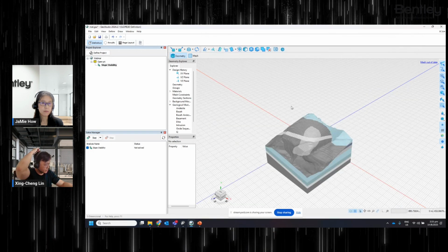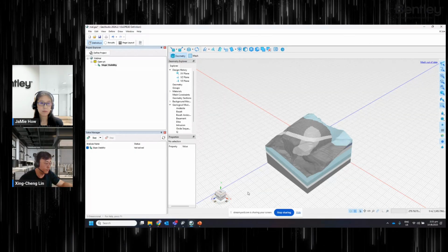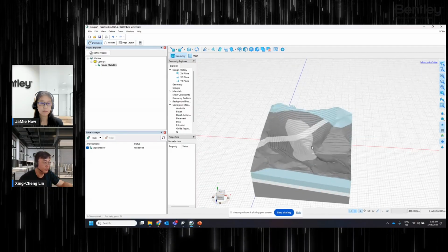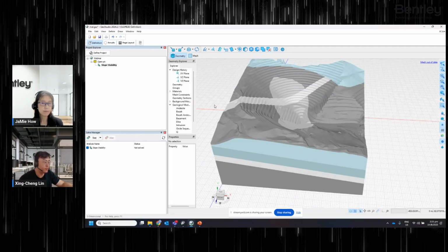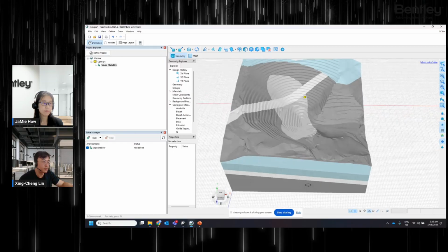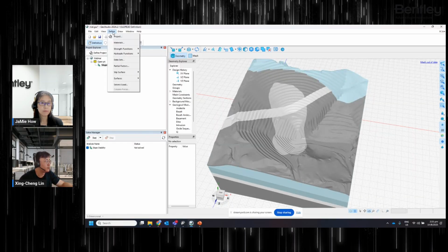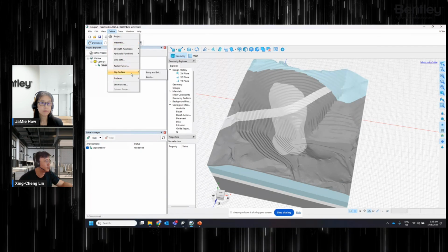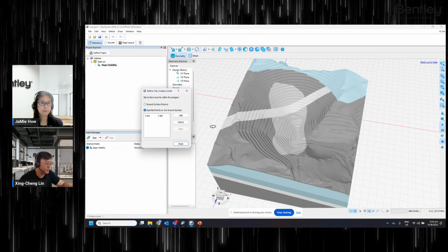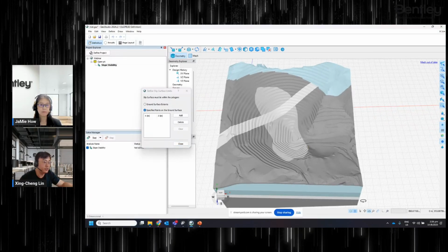So next we're going to draw the slip surface limit to define the extent of our slip surfaces. In this case, I need to reorient the model. All right. Right, go to define slip surface limit. Then I'm going to use the mouse click to define such a search zone.